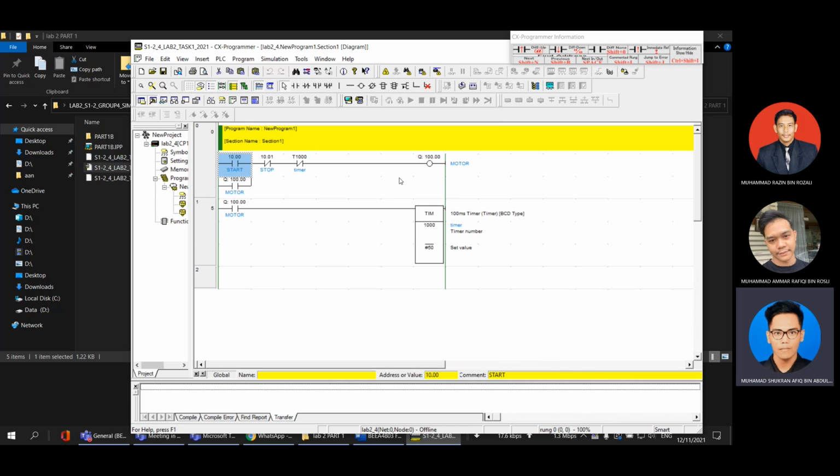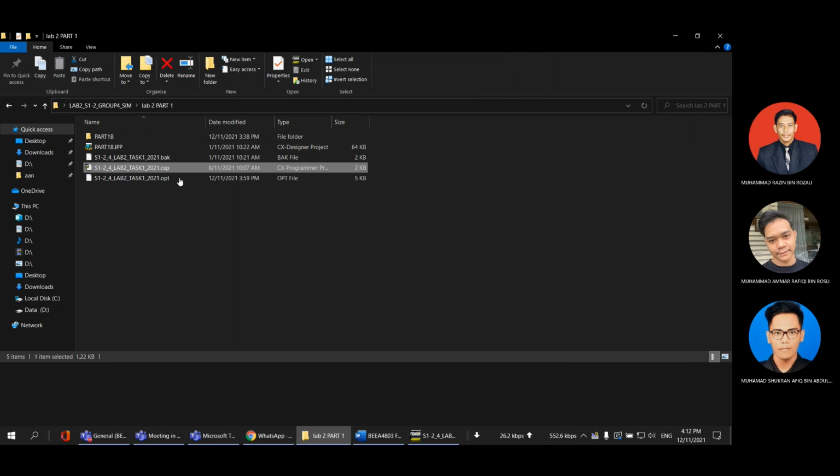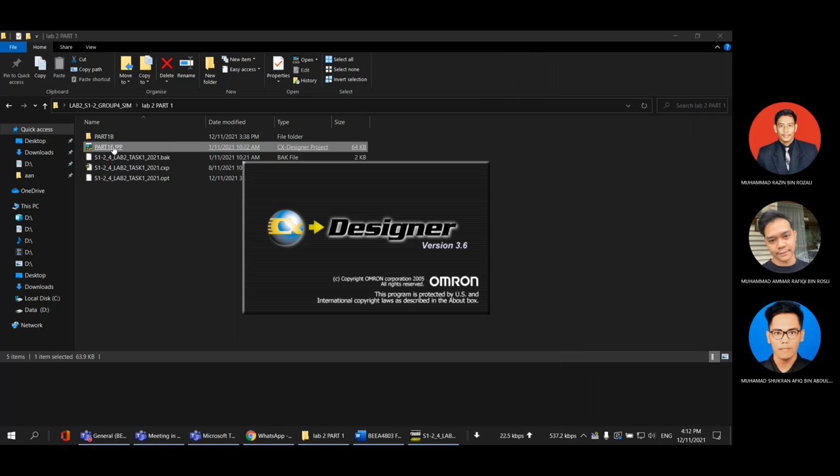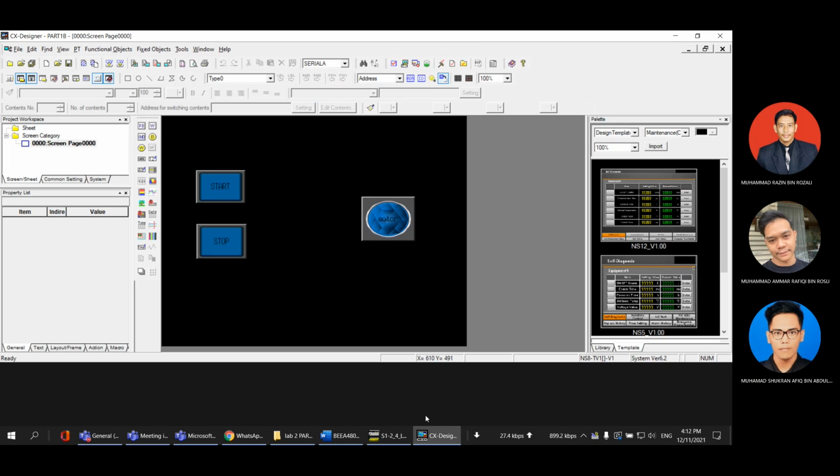This is the CX Programmer for this task 1. We have added the timer here. Now I will open the CX Designer. This is the CX Designer. Now we're gonna link the CX Designer and the CX Programmer together.